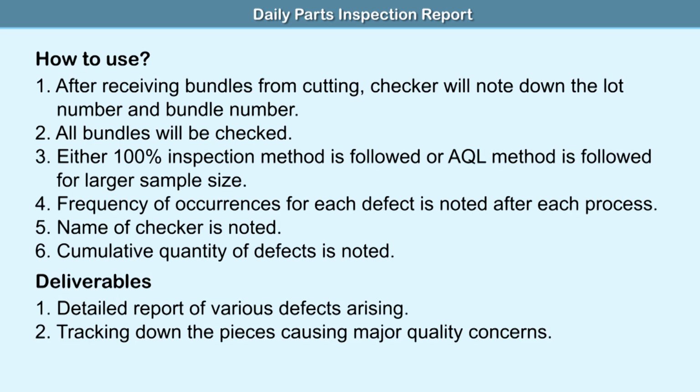How to use. After receiving bundles from cutting, checker will note down the lot number and bundle number. All bundles will be checked. Either 100% inspection method is followed or acceptable quality level method is followed for larger sample size.